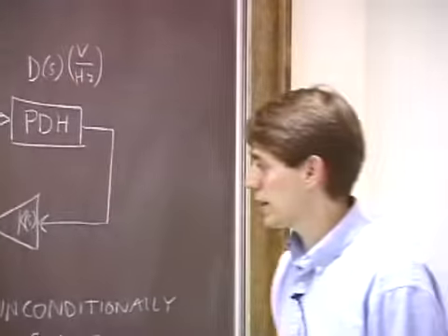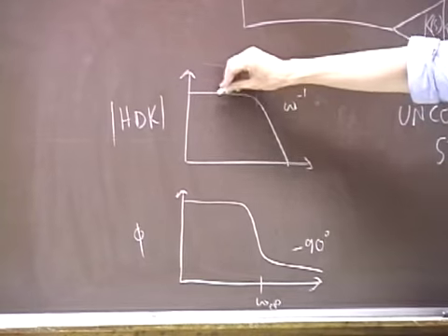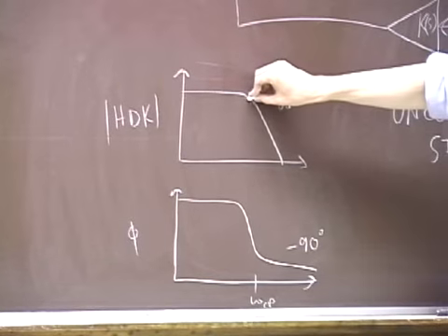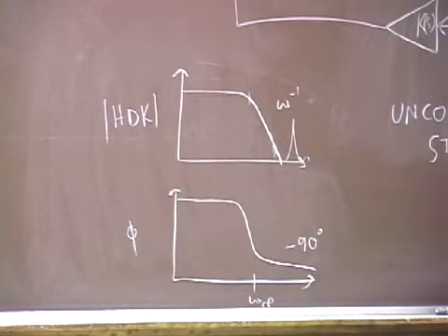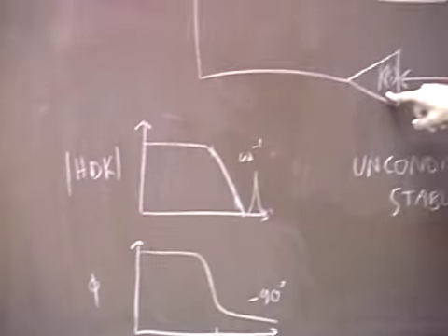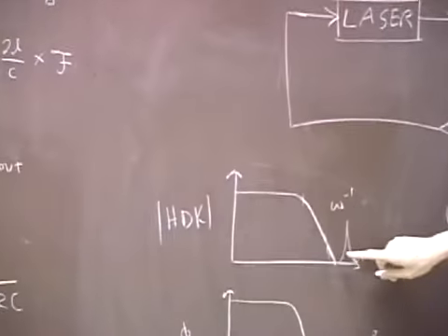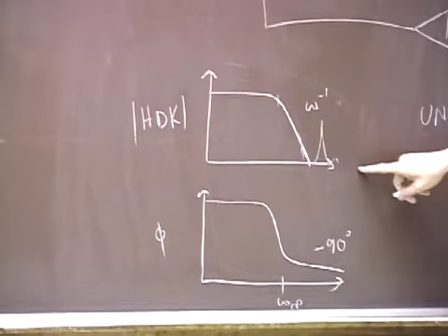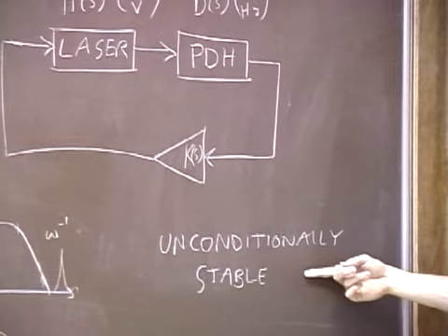And so what you would really have in real life is nice predictable behavior up to the first pole, and then you'd have additional poles and maybe even mechanical resonances at higher frequencies. So in real life, what we do is we introduce a pole in our amplifier at fairly low frequencies, low enough that we suppress all of the gunk that happens at high frequencies, and then we come back and we produce another unconditionally stable servo on purpose.